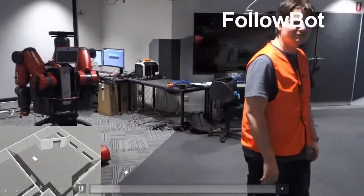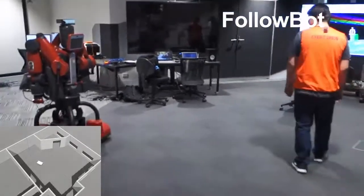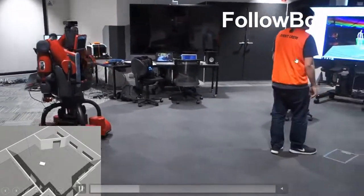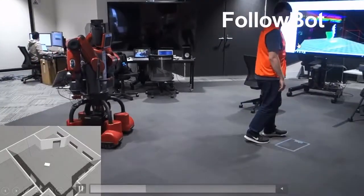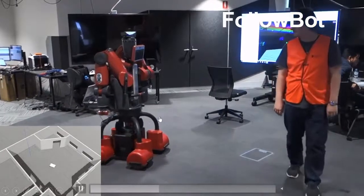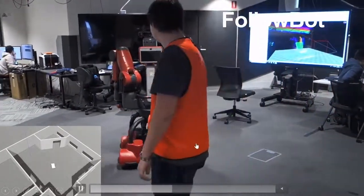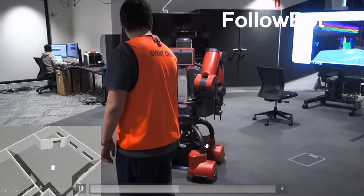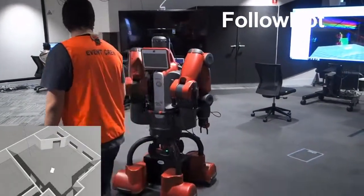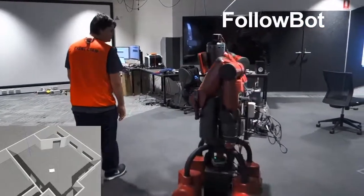A live test of the Followbot prototype where Rosie follows the user is shown here. The Followbot uses a colour detection algorithm to detect the orange vest. It sends a command stream to the mobility base to rotate and move towards the vest. A safety component intercepts the command stream and uses data from its 360-degree LiDAR sensor to ensure that the robot does not collide with any detected obstacle, including a human.